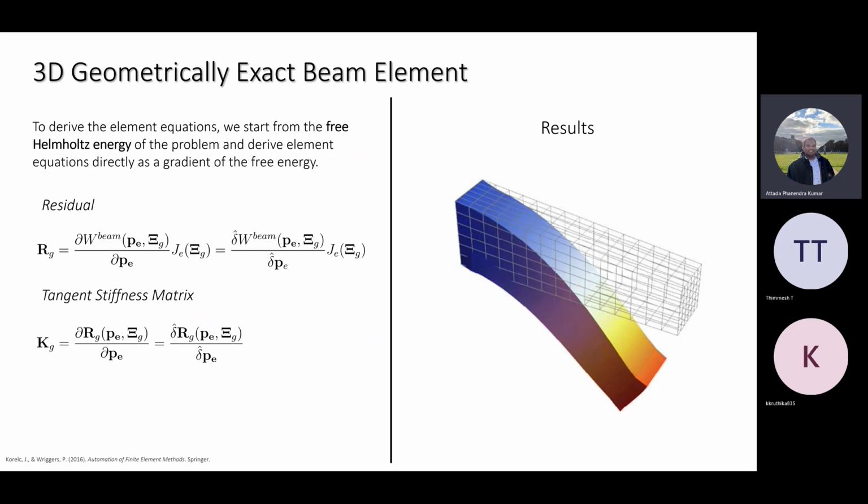the simplification is also in the process of deriving the final algebraic equation. If you remember, the simple process of FEM is that you have a variation statement, you minimize it, and then you discretize the equation and come up with the algebraic equation. Effectively, what you're doing is minimizing the strain energy with respect to the primary variables, and the tangent stiffness matrix is nothing but minimization of residual with respect to the primary variables. So you input the syntax in this way, and ASGen helps you with calculating the element stiffness matrix.